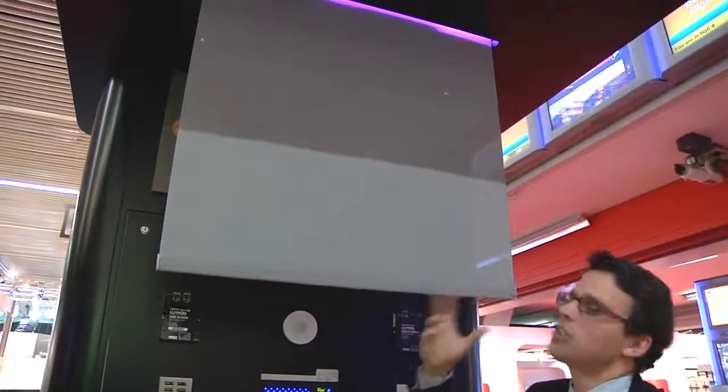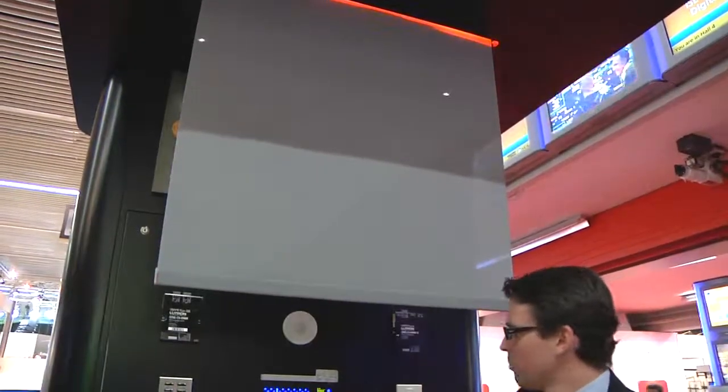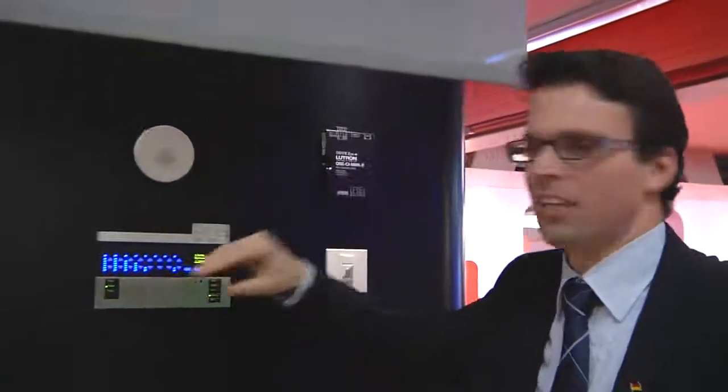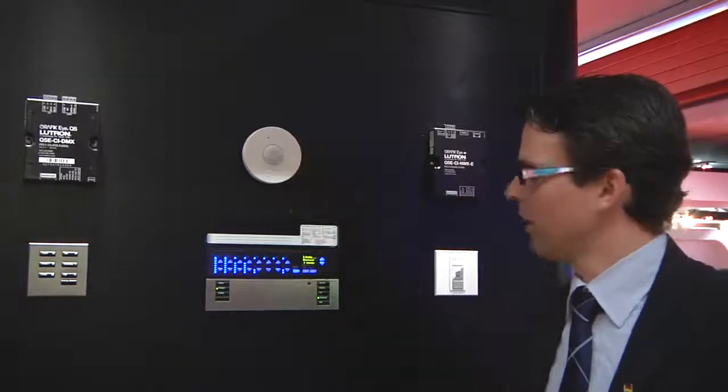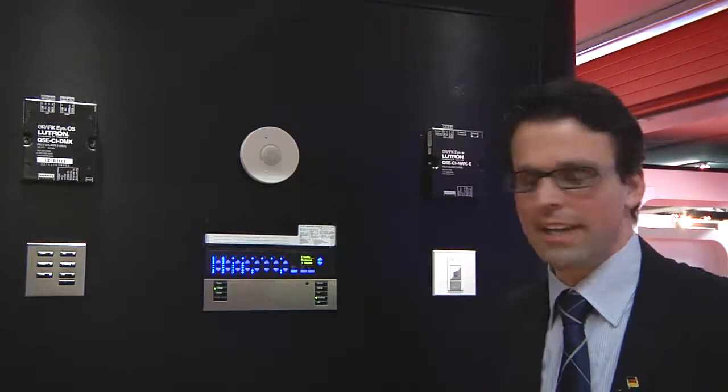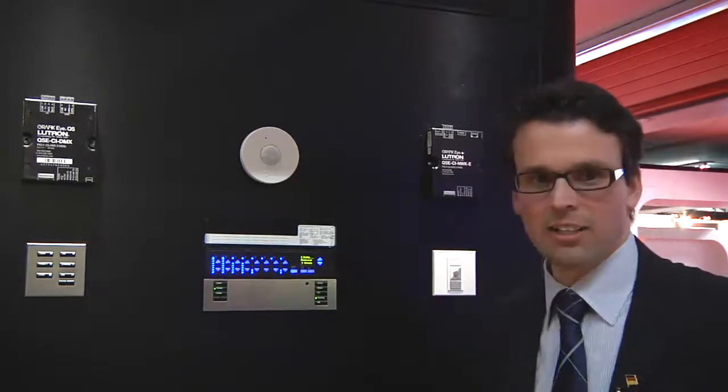So I have recreated RGB, and if I change the color, press this button, you can see on the top of the shade, the blue LED mix is on. I can select another scene from my Graphic Eye, and the color changes to red. So again, in a very simple format, without any programming, I can control LEDs, I can create colorful scenes, I can create a color sequence, and this really rounds off the package with the Graphic Eye QS capabilities in terms of the lights, LEDs, and integration with Ethernet.